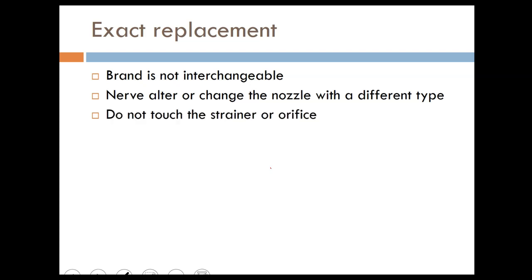Do not touch the strainer or the orifice. Try to minimize touching the nozzle. Use a clean rag to put it in place. And if you drop it, sorry to say, you have to change it, because that will change the geometry of the nozzle.